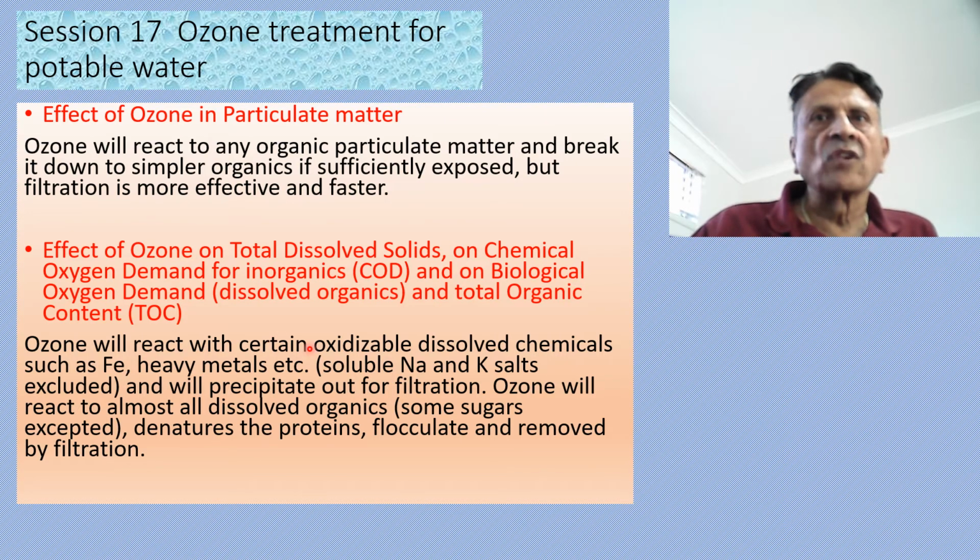Ozone will react with oxidizable dissolved chemicals such as iron, heavy metals, etc. Soluble sodium and potassium salts are not reacted with, and they remain if they are in solution. The heavy metals, iron, zinc, etc., will precipitate out for filtration.